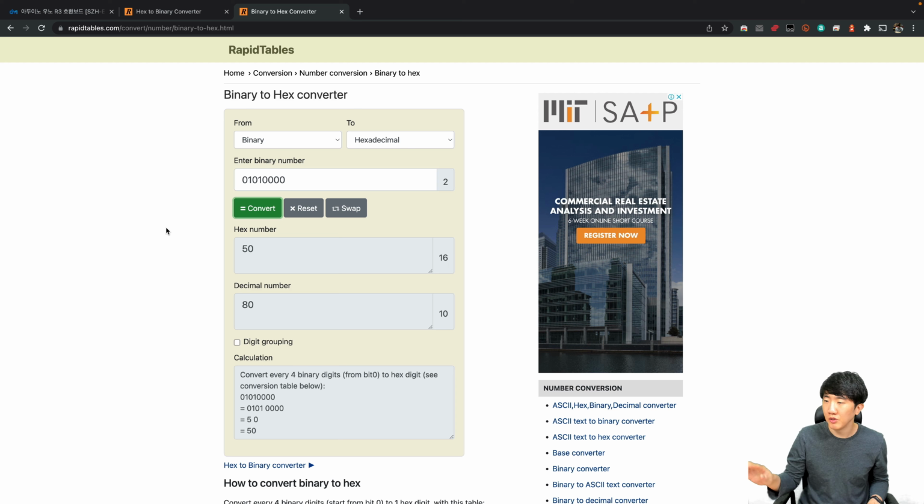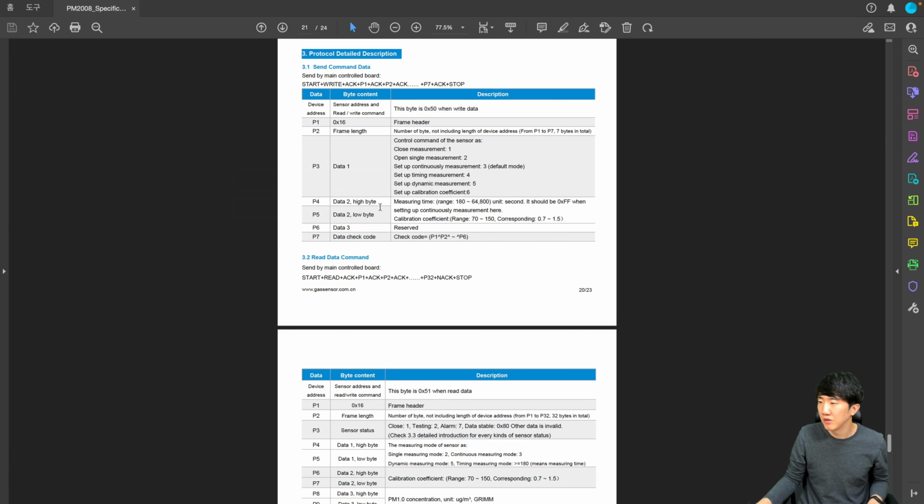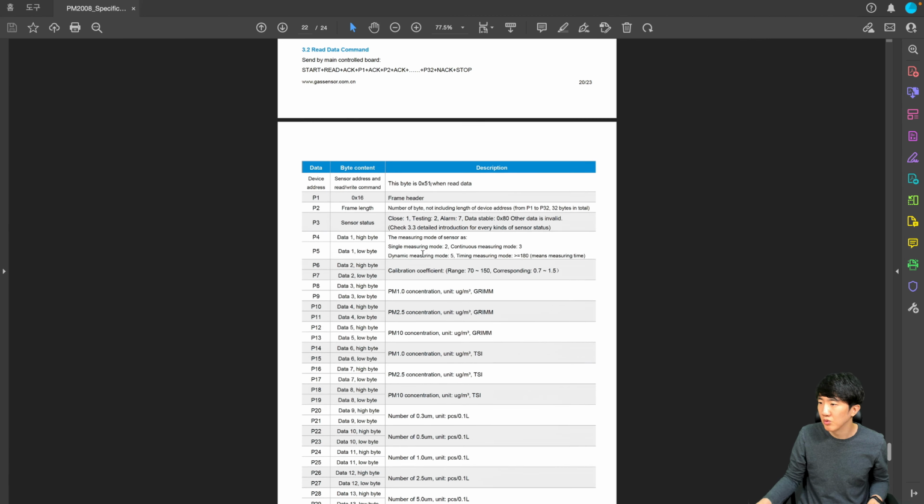However, the commands can vary slightly depending on the specific hardware platform. In the case of Arduino, it automatically appends 0 or 1 when reading or writing. So we only need to know the actual address when looking at datasheets. The address is indicated in the first part as being based on the I2C standard, specifically stating that the address is 7 bits, so it is 0x28, but here it is indicated as 0x50 and 0x51, which is different. You just need to understand that this is the reason for the difference.